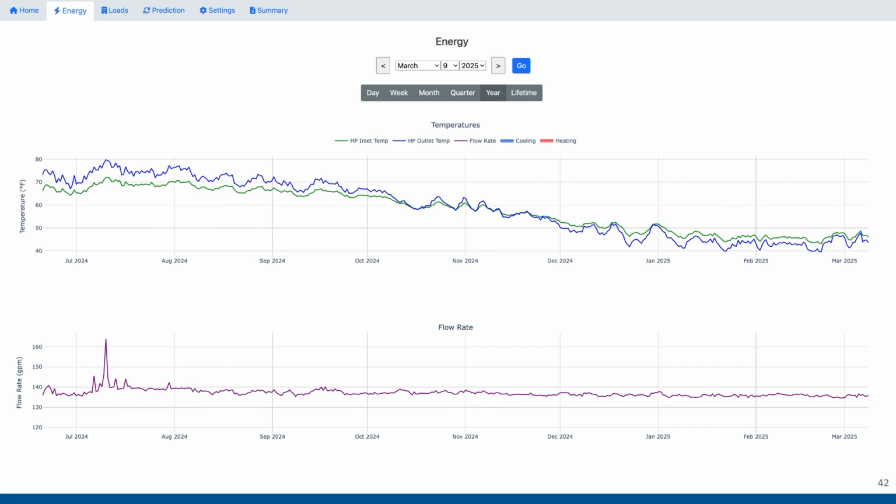You get your typical sine wave of your geothermal system, but one thing that stands out here is when you think of your ground heat exchanger design, your typical goalposts for your design temperatures are 90 on the upper end-ish, down to 35 or 40 degrees Fahrenheit in the wintertime. So those are sort of your goalposts. And the green line here represents the ground heat exchanger temperature. So we're only getting up to around 70 in the summertime, which is fine, but a little bit under what's expected. And then in the wintertime, we're only getting down to 45, 50.